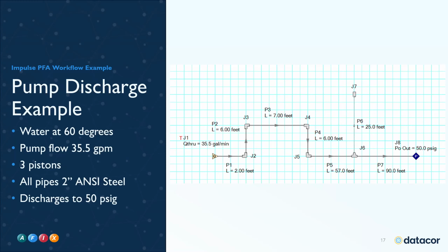It might be helpful to grab a screenshot of the dimensions shown here on the right before we switch back to Impulse. And if you miss anything with the pump setup or you want to work ahead, I'm going to use the same inputs as the pump in the US positive displacement pulsation steady model from your examples folder.